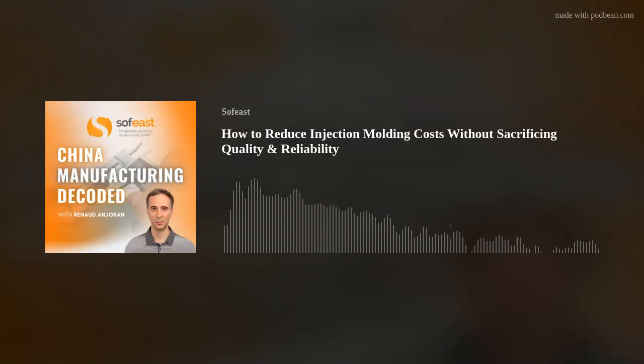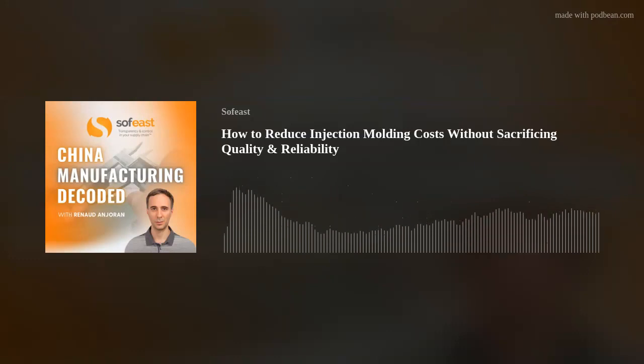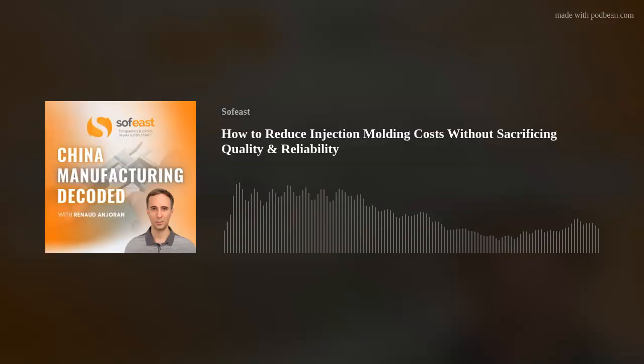If you are running a part that's the same geometry, same shape, but you're running different colors, and we have quite a few of those products running in our place at the moment, same product, but produced in 6 or 7, I think we're up to 12 different colors now, each time a color is run, you need to purge out the machine. That takes a long time.